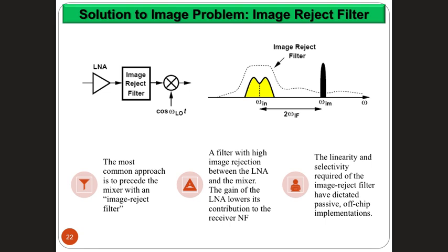Accordingly, you know that anything which is double that intermediate frequency away from you is going to be an image for you. So you filter out those signals. Typically, the distance here is a trade-off.